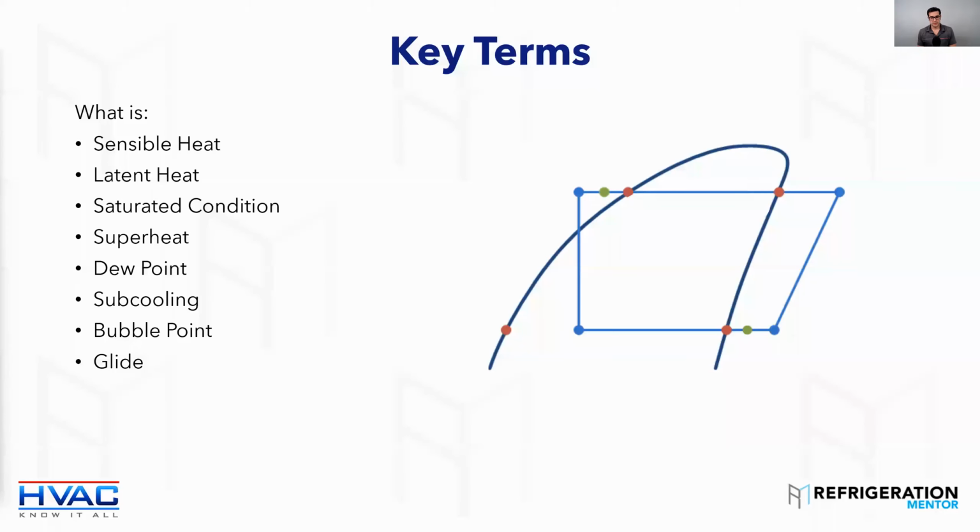Yeah. That's correct, but there's something you just missed when you said that. Does glide refer to specifically just the evaporation stage? No. I can read you something. I don't know if I should read it now or wait till we chat about it, but glide is the refrigerant itself. It's got different components to it. Basically it's the boiling point of the least volatile across to the most volatile, and there's a gap in between the two.